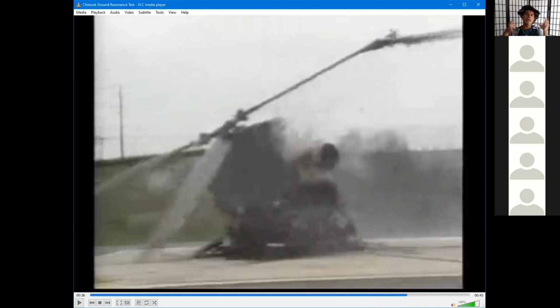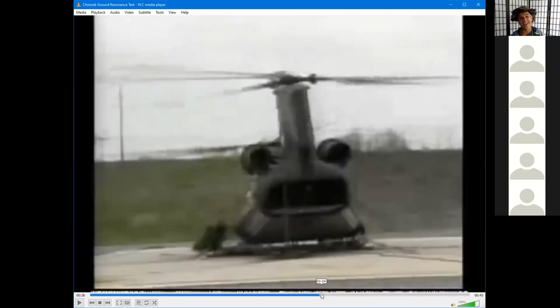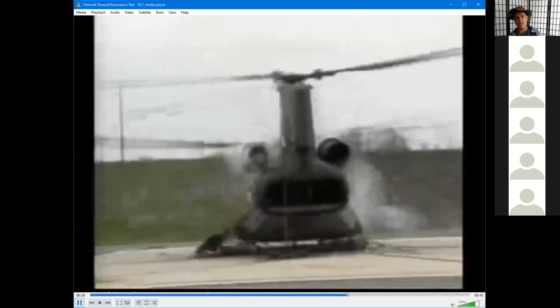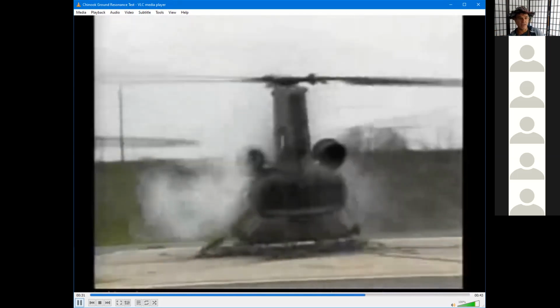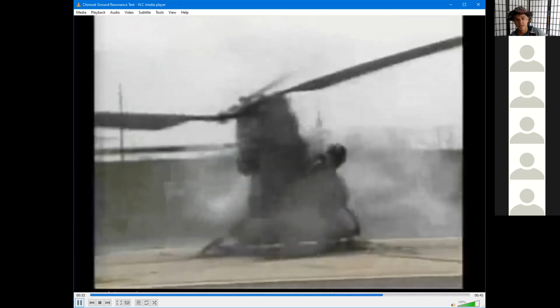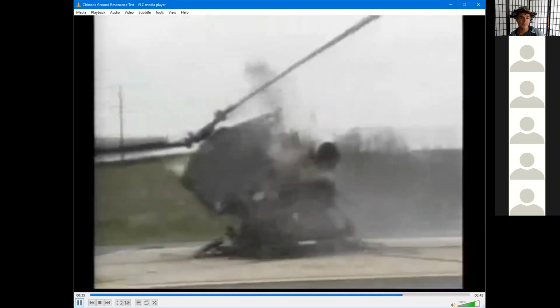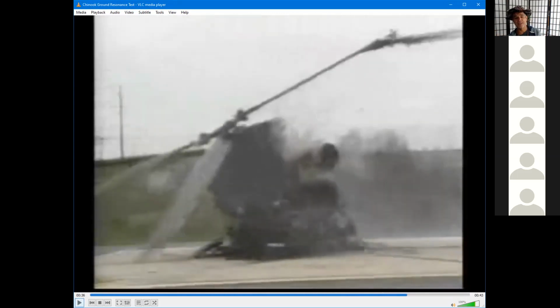Even something like a helicopter, or in this case, the spinning part, has a natural frequency that it tends to oscillate at. As this blade is slowing down, at some point it's rotating at just the same frequency, which causes the amplitude to increase to the point where, bam. Right, really glad they're testing this out.